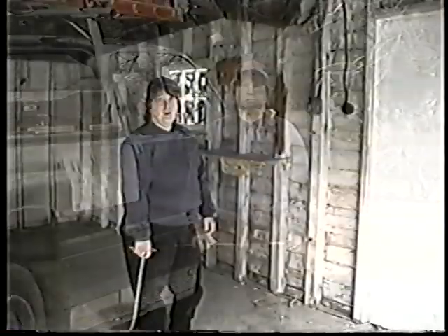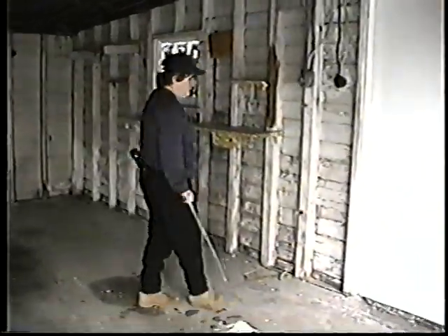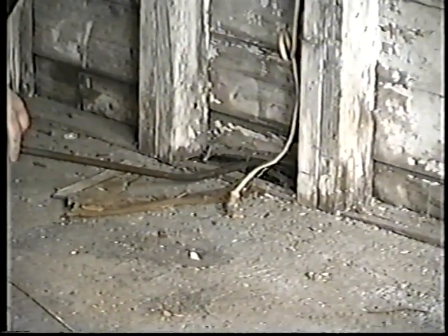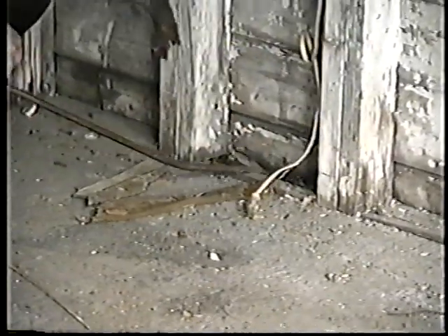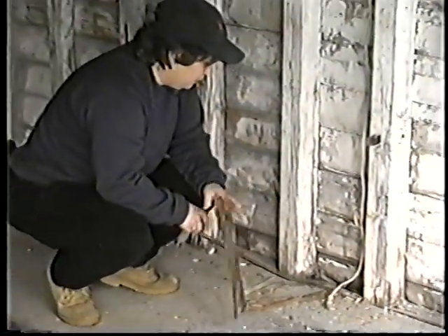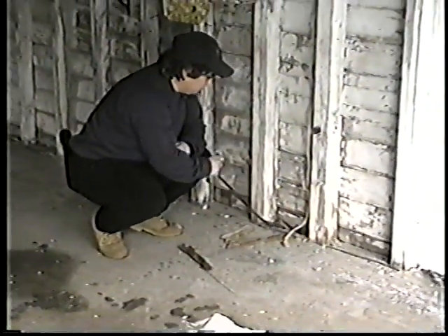We're in the garage and we're checking out the sill plate. It's a wooden sill plate, and when we poke, which is part of what the inspector's job is, if it breaks apart, it's then their job to decide if it's carpenter ants, termites, if it's just wood rot, or if it's something that needs to be addressed. This particular damage looks to be termite, and it's also mixed in with some wood rot.